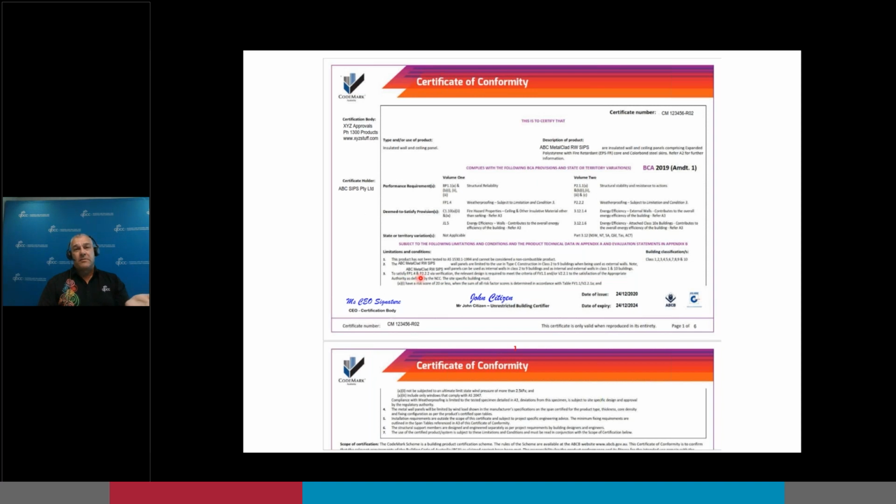Now that weatherproofing part, as I mentioned before, you as architects will be familiar with, because in the NCC up to the 2019 version, so from 2017 to 2019, if you did a class 2 to 9 building, it was mandatory that you had a performance solution for weatherproofing, as there was no weatherproofing deemed-to-satisfy. Obviously the current version has a couple of items, but doesn't cover everything. So the thing we were trying to point out for this one is to have a look at your limitations. It's got the weatherproofing, and you've got to do the risk score that they have for the verification method.